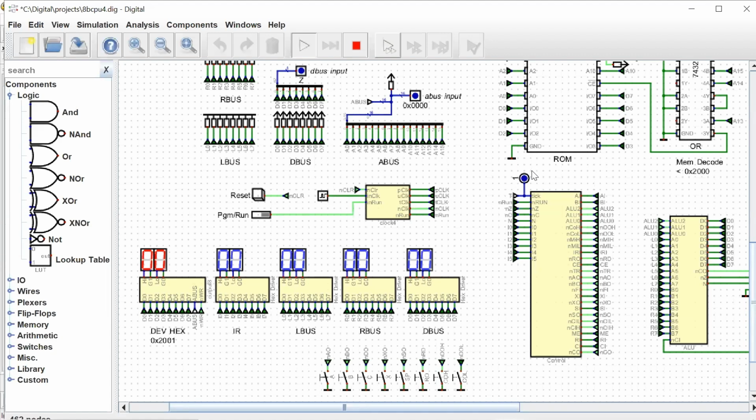Now we're at step 2 in our fetch cycle, and we can see it's counter out low, and our memory in low signal is raised, and we still have ALU 1 and 2 signals raised for the OR function.